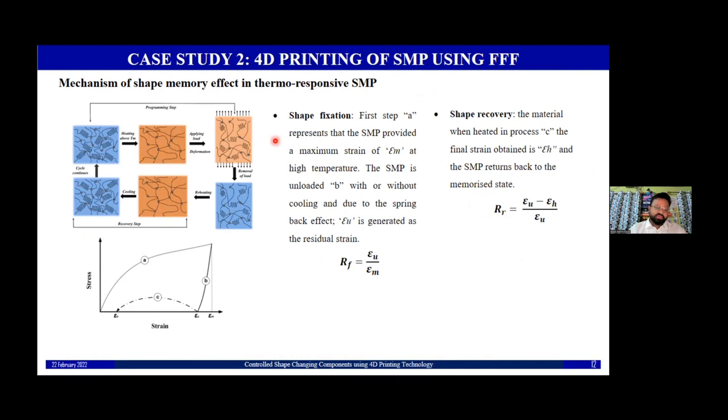Any thermoresponsive shape memory polymer has some common structural features: a shape fixing part and a shape switching part. The shape fixing parts are the structural domains or net points in the SMP network that maintain the dimensional stability during deformation. The shape switching parts are the long polymeric chains between the shape fixing parts that are stretched during the deformation. These shape switching parts generally store the elastic energy and are responsible for the shape recoiling of the